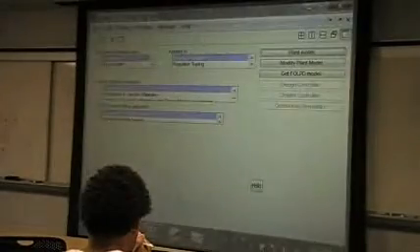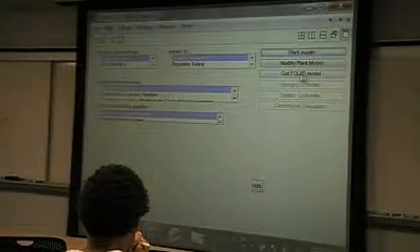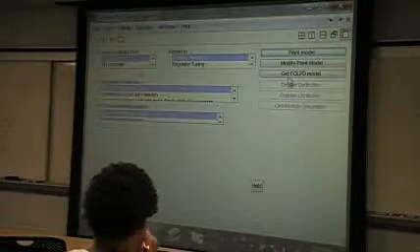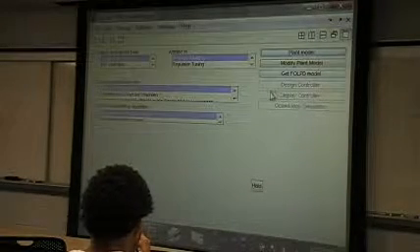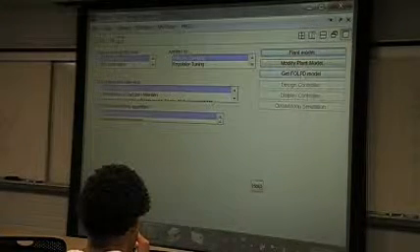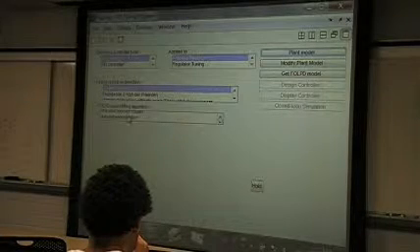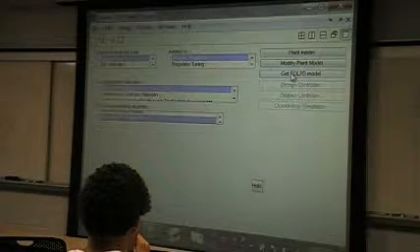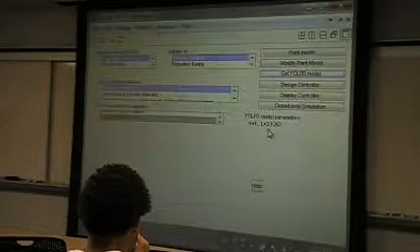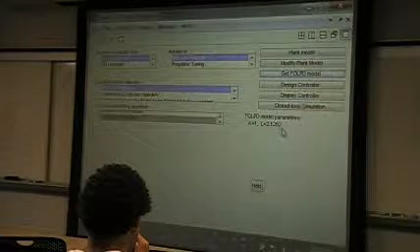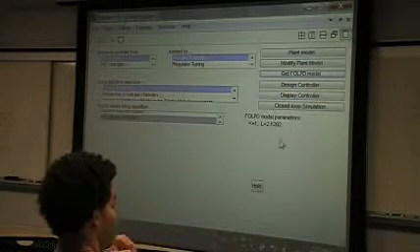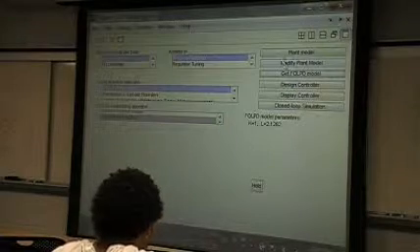And you have entered the plant model already. Then the next thing we need to do is to get the FOPDT model, where we have to get the K, L, and T parameters for the plant. We can use approximation methods, such as suboptimal optimization or model reduction, and then click this button. So you can have K, L. So where is T? I think the display might have problems.